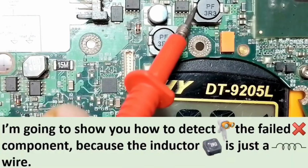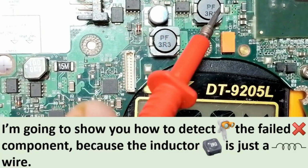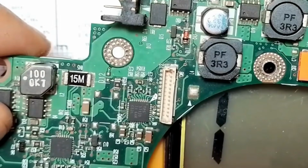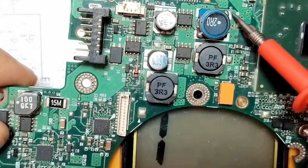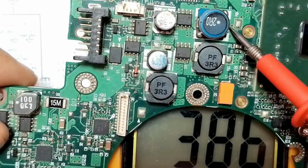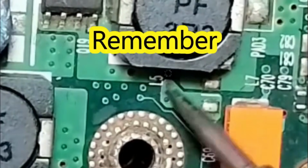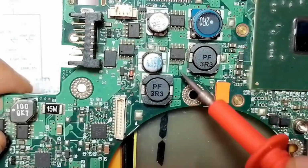I'm going to show you how to detect the failed component, because the inductor is just a wire. It's not the shorted component, but around the inductor there is a failed component. So for this inductor, for example, we don't have a short circuit here. We have here L6, as you can see. Basically, these two inductors belong to the same circuit. So we have L5, okay, remember L5, and here we have L6. These two belong to the same circuit.